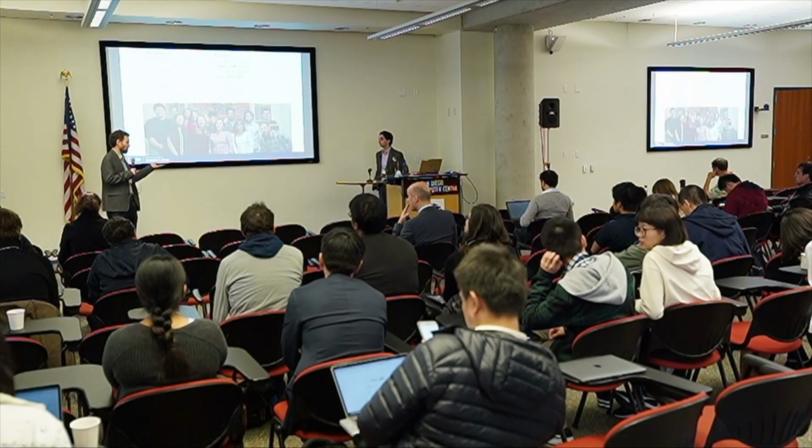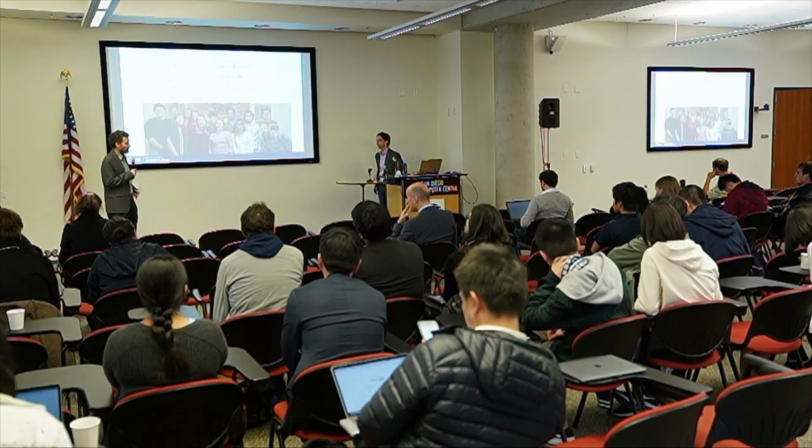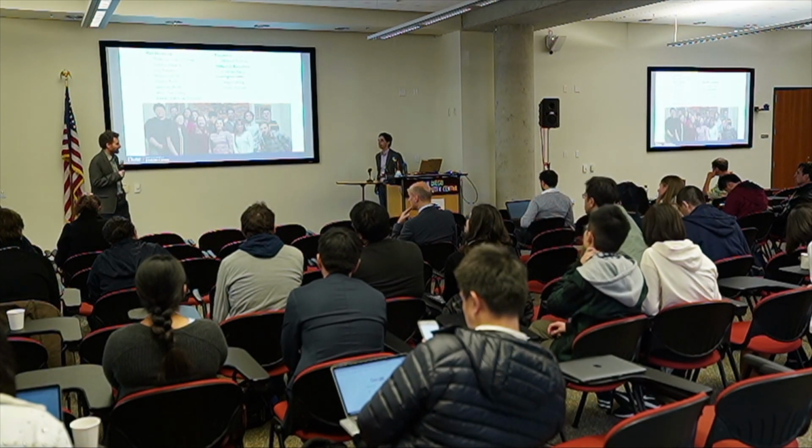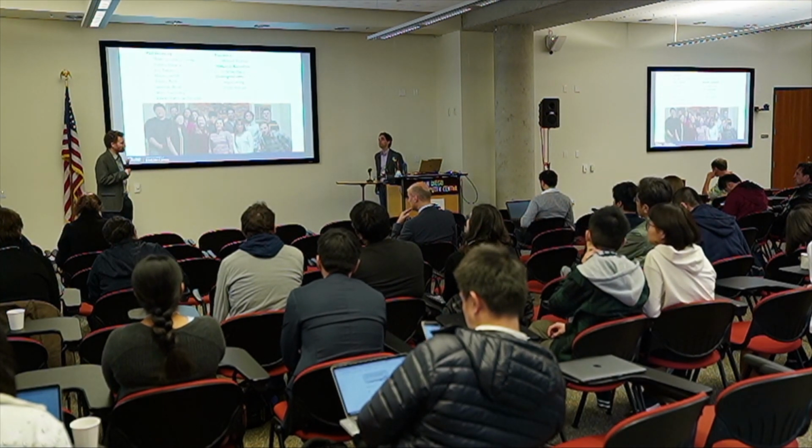So with a 25 micron pitch and also non-contact capacitive sensing, would that be sufficient to get spike resolution? That's a challenge, yeah. I don't know if non-contact, maybe. That's very challenging at that spatial scale. So we're going to try strategies where we do through-hole and contact electrodes, Faradaic electrodes, in order to get to that really fine pitch. But if we're designing devices for a medium scale pitch, I think the capacitive sensing allows us to not have as many challenges with long-term implants.